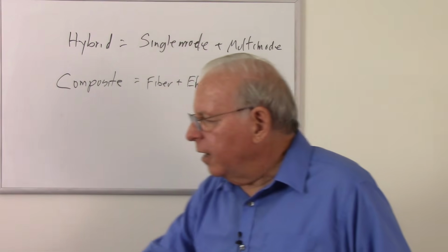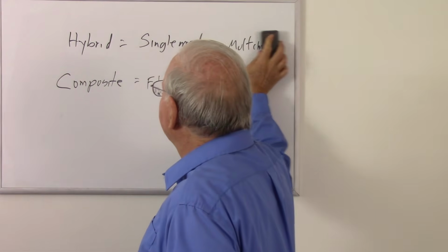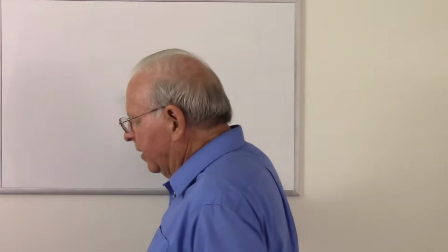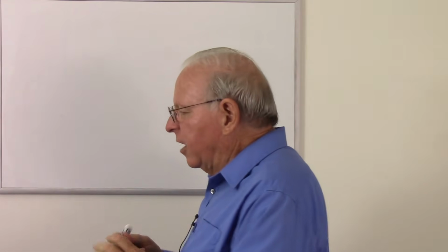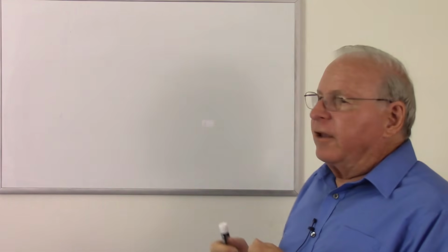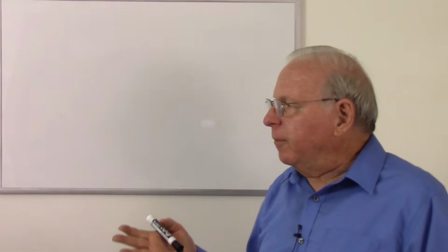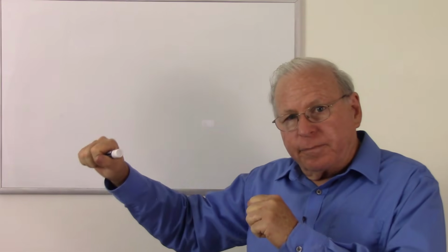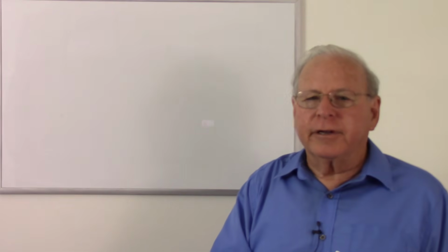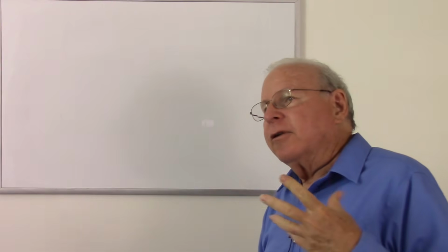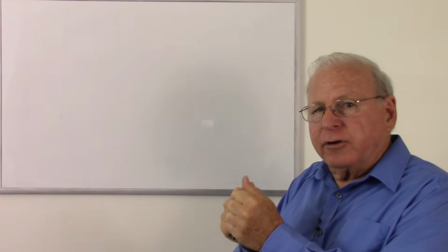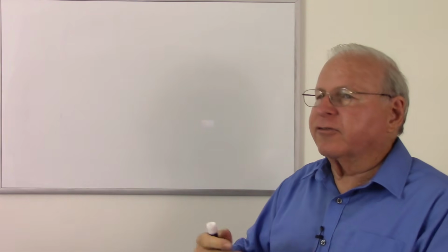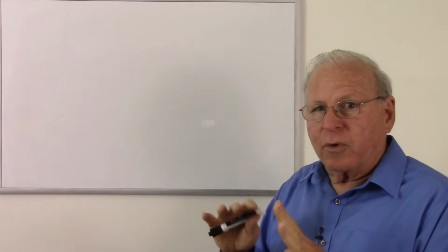Okay, just before we go on to the next thing, well, actually the next thing is a little bit to know about installation. So if you happen to have to help install some of these cables, what you need to know is you're going to possibly be pulling cables through conduit. And if you do, you need to use lubrication. You don't want to put too much stress on those cables. You want to limit the stress. There's a lot more to know about this, but just real quickly, limit the stress.